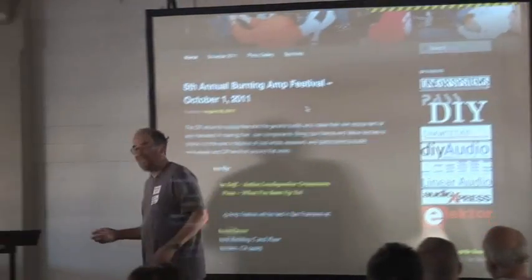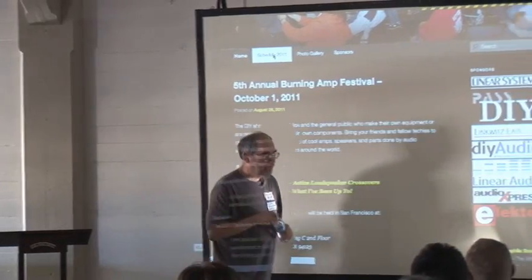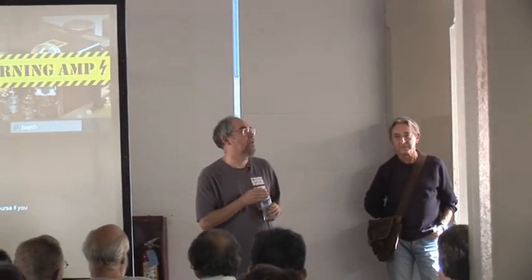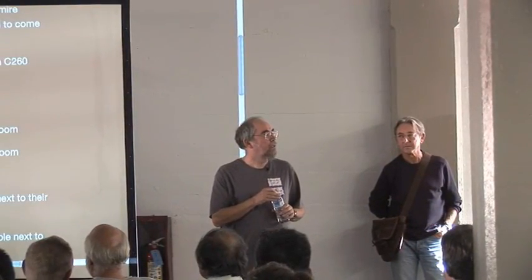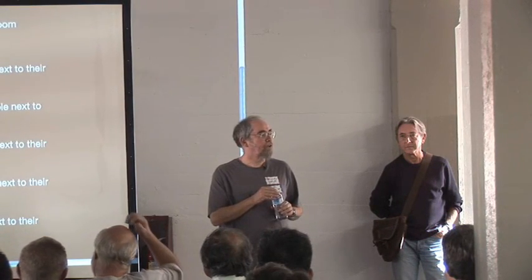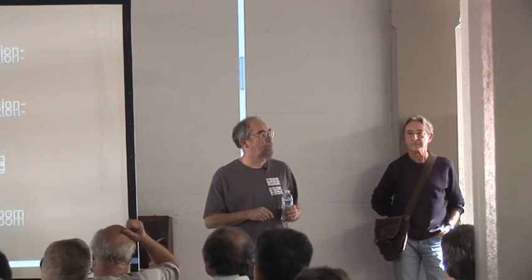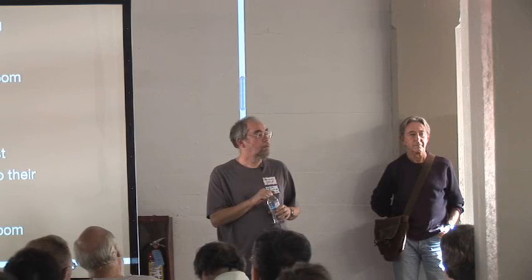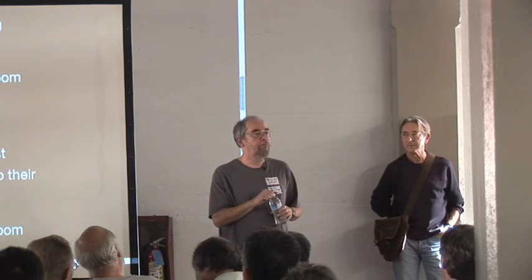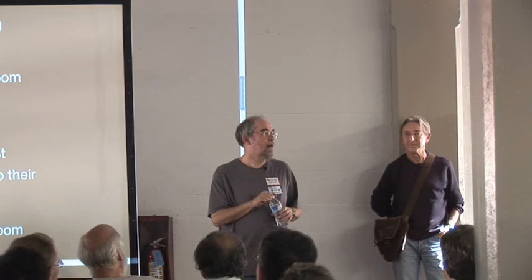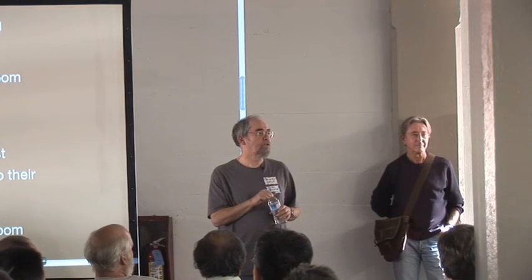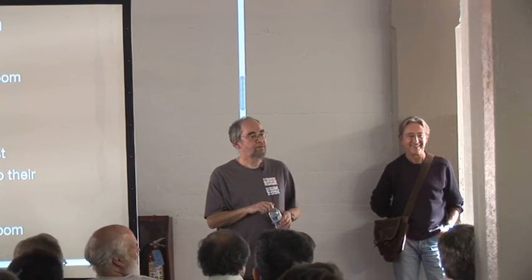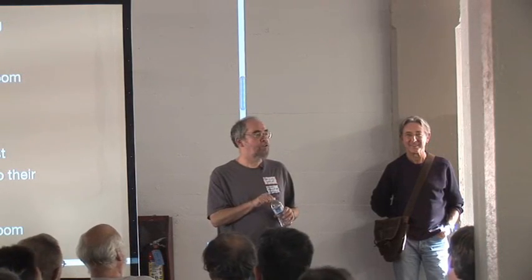When I first worked for Cambridge Audio, back in the days of the P60 and the P100 and things like that, I mean, this is 1975 or thereabouts, the technical director thought that would be a cracking idea. We would put a triac across the output and fire it when things went wrong, and then that would be fine for the loudspeakers. Well, maybe. It was pretty bad for the amplifier. You need a really big triac if it's going to work more than once. Well, they just sacrifice the triac. Well, yeah, but you also sacrifice the PCB tracks and the power supply, and we sacrificed pretty much everything, really. We had to destroy the amplifier in order to save it.